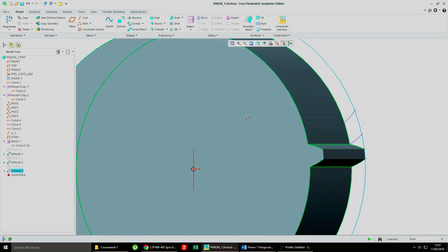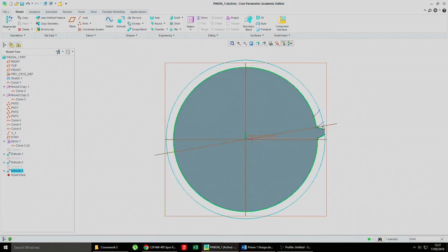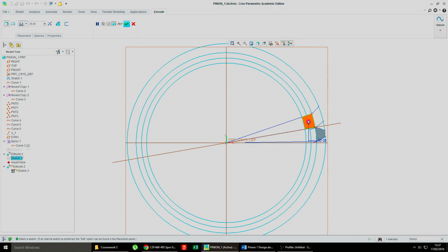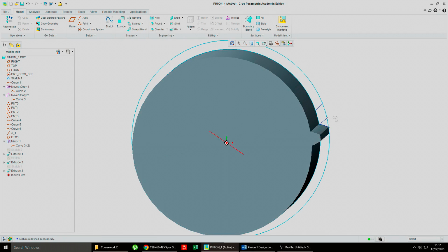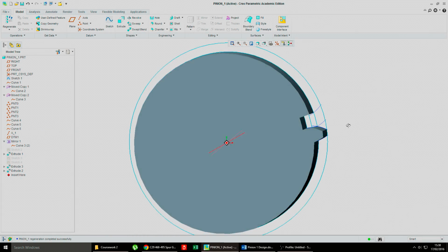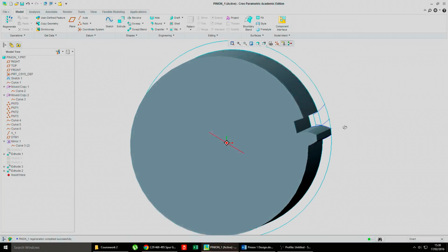Okay, now get to front. Now you want to remove this little material thing that you've done. The way to do that is, it's probably not going to work right now because I've done that the wrong way around, but you might be able to get away with it. Click remove material, press OK. Yeah, it hasn't worked, so just literally drag your extrude down one like that and it should do it. There we are. So that's what you're looking for. That is going to be the profile of the first tooth and the first root, I guess.